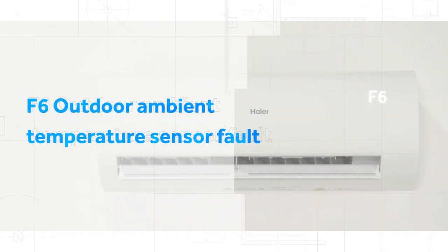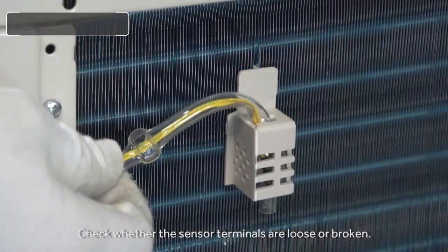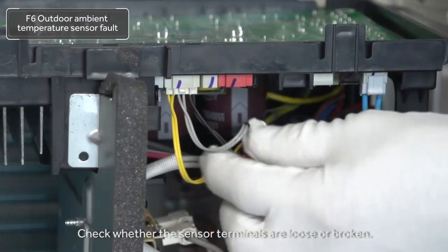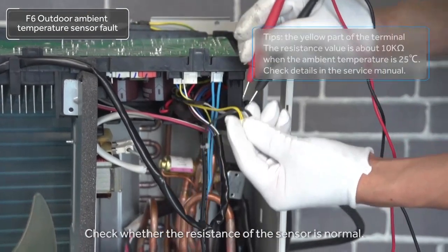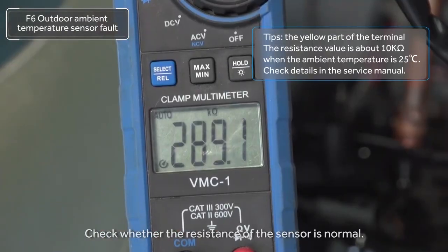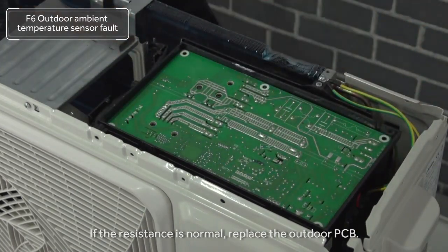F6 Outdoor Ambient Temperature Sensor Fault. If the indoor unit display shows error code F6, it is the fault of the outdoor ambient temperature sensor. Check whether the sensor terminals are loose or broken. If the sensor terminal is okay, check whether the resistance of the sensor is normal. If the resistance is normal, replace the outdoor PCB.